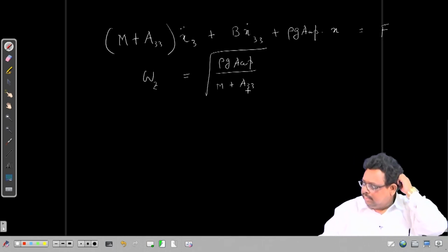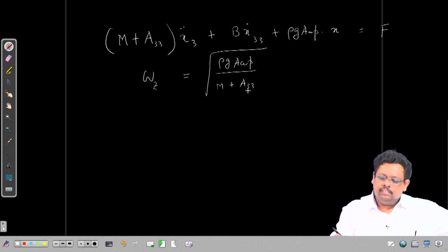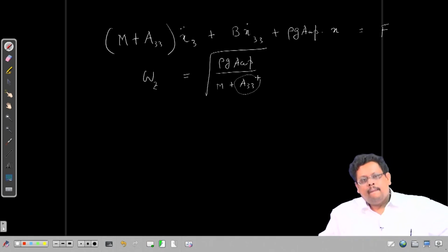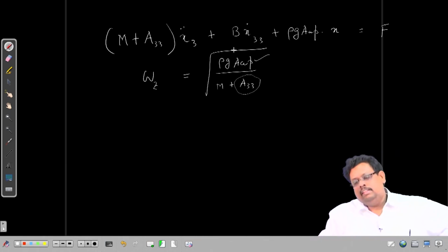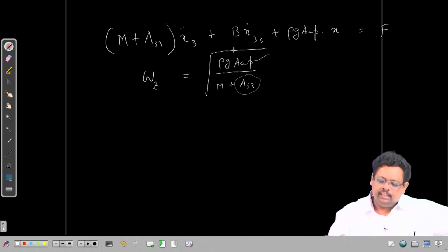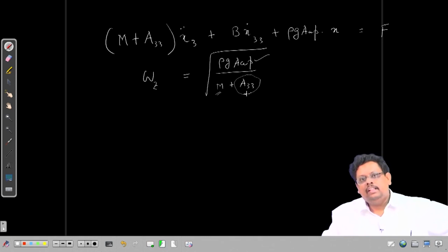In this numerical ship hydrodynamics class, we are going to discuss how we get the heave added mass A33. Suppose someone asks how to estimate the natural frequency for heave. A_WP is a geometric property, rho is the density, g you can approximate as 10 or 9.81, and m you know, the mass. The only term coming from the hydrodynamic side is A33.